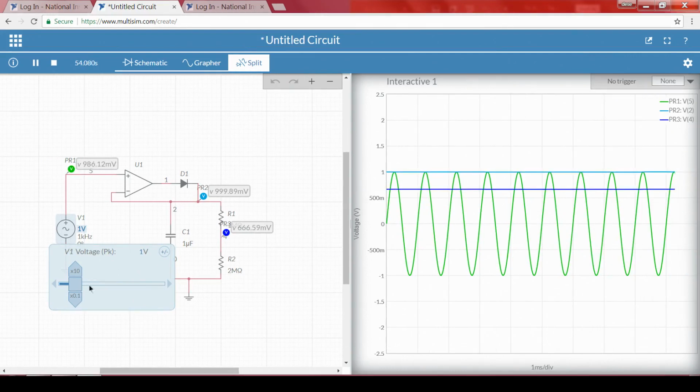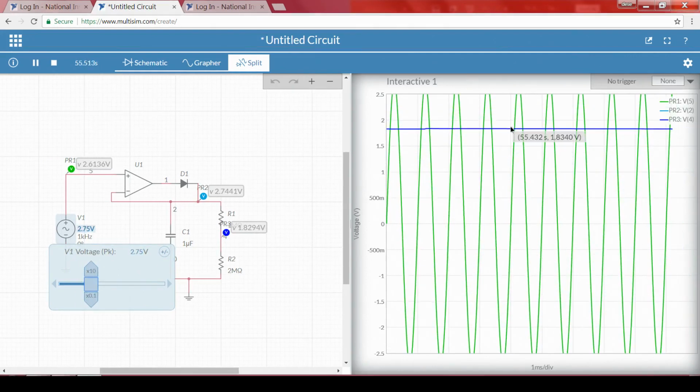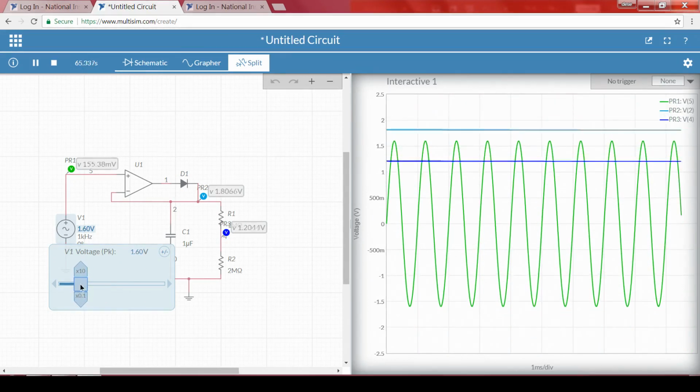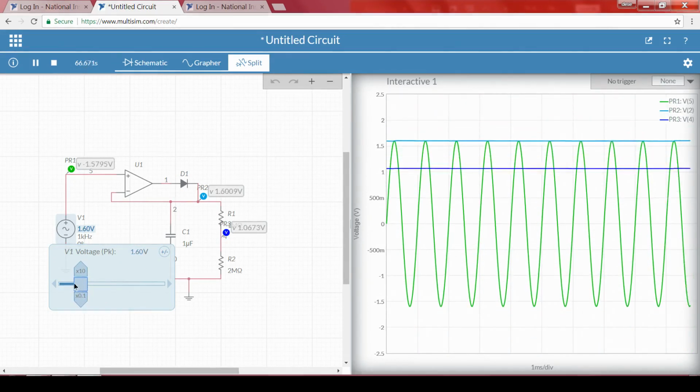If the input voltage is changing, even the threshold value will change, and how fast it changes depends upon the capacitor value that we have chosen there. In this case we have chosen a 1 microfarad capacitor. So, another requirement for the signal conditioning or signal processing circuit of our ECG is completely fulfilled using this circuit. Now, what is the other part?